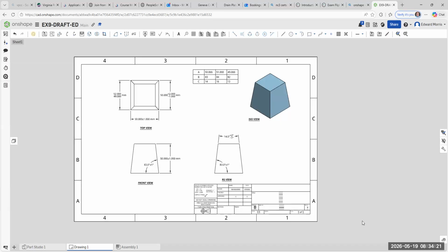We learned how to create a draft angle, and I gave you some applications for that. I gave you making molds and castings. And then I said also with forgings, if you come down and you press two pieces together and it's at a 90 degrees angle, it's not going to come apart. It's going to be stuck in your tool. If it's a 90-degree angle, you have to have a slight what? Draft angle. Does that make sense?